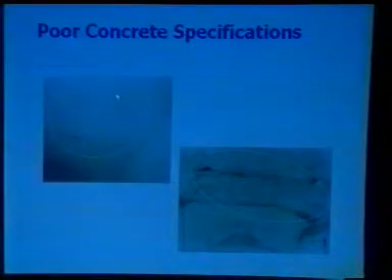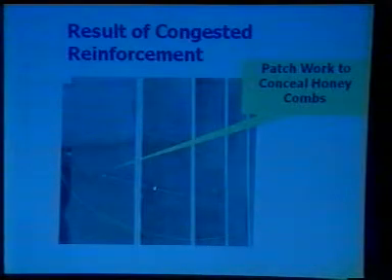Now, gentlemen, this is a very commonly observed site. This is the underside of an RCC overhead water tank. You have poor concrete, reinforcement exposed. This is a very commonly observed condition. Now, you see this patchwork, and all this is to conceal the honeycombs.